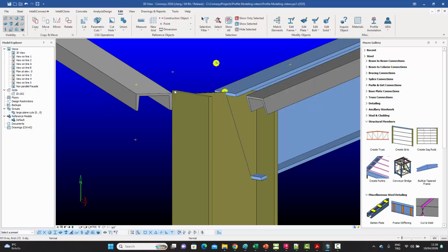And for this one, what I need to do is I need another point which is 120 away from that point, and I want a lip point 20 millimeters below that. So let's go to the extension point again. This time say minus 20, and I can just go from here to here to create that point.